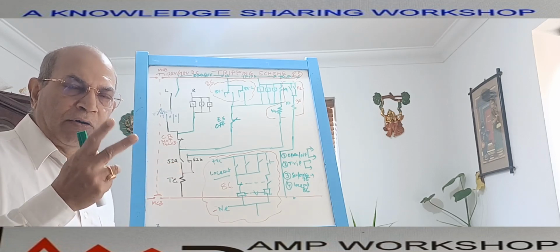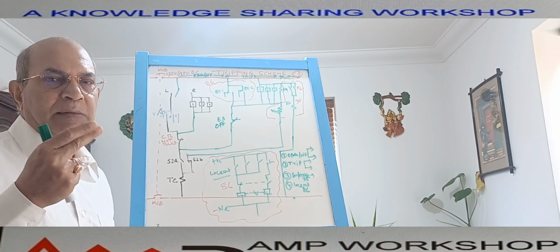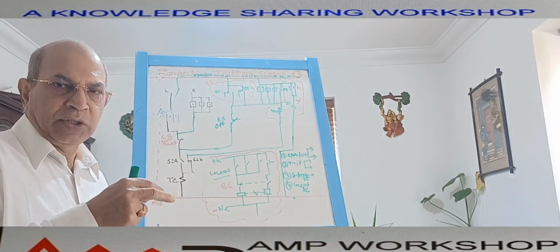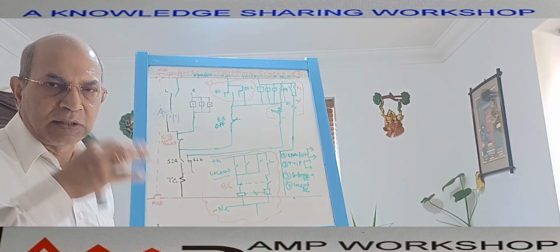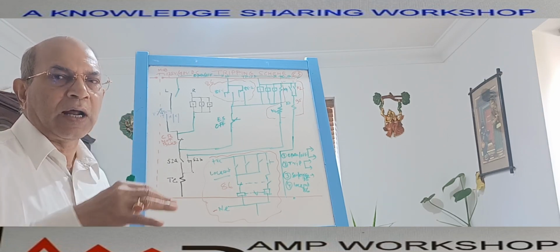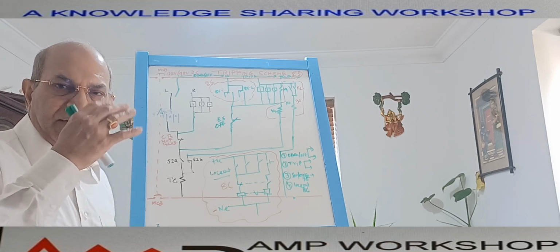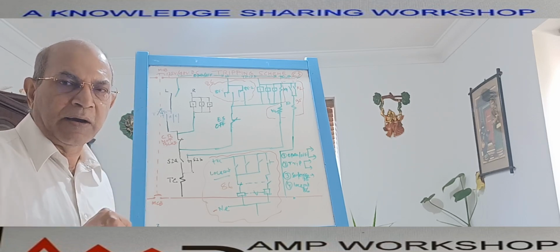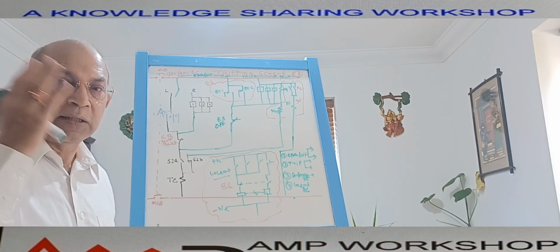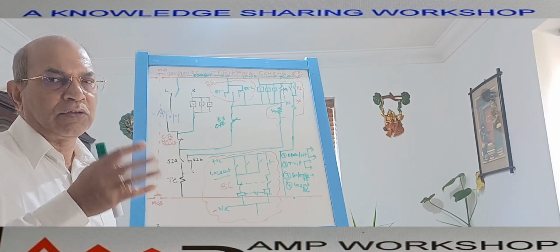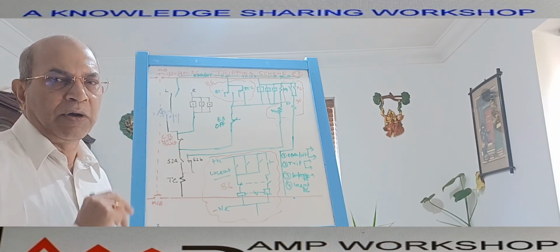So this fault condition tripping can be classified in two parts. One part is a fault on its own circuit, and the other is tripping of this breaker due to another device fault, other equipment fault, or some other reason. So an emergency shutdown signal can come, a fire and gas signal, which is also an ESD signal, can come, or an inter-trip for another circuit failure. This inter-trip can come to this breaker, and that is also a trip. So these are the two tripping operations.